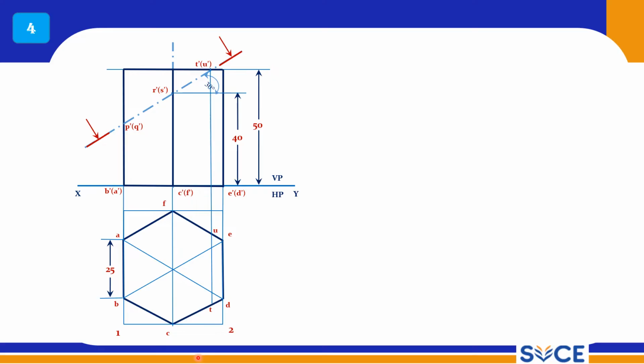This is TU, and you have 1, 2, 3, 4, and now these points should be projected here. To project T and U, they should be projected from the top view, whereas P, Q, R, S can be projected from the front view.